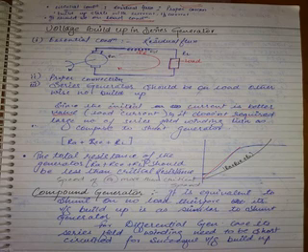For example, if you want to calculate the critical resistance of this generator, how do you calculate it? You have to plot the OCC. You cannot plot the OCC for a series generator simply. If you want to plot the OCC, then again you have to separately excite it. The field winding should be separated. You have to apply voltages and connect a voltmeter. So if you have an OCC, again what you will do, you will plot a tangent. You will draw a line like this. So RT by OT, same process. Then you will say, this is the critical resistance of the series generator. And the total resistance of the machine and the circuit should be less than the critical resistance, because the initial current is flowing through the entire circuit.